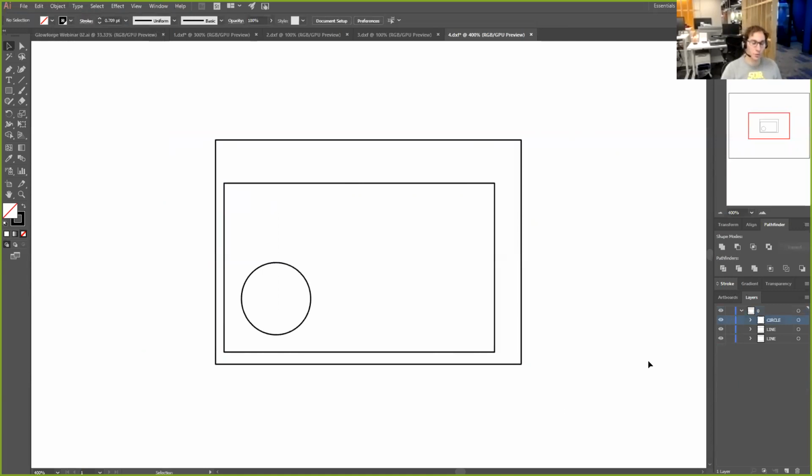In truth, this will work even if you don't join the path altogether. It's fine. It'll work for the score and for the cut. Actually, for the web interface for Glowforge, it'll work no matter what. But honestly, it's a much better practice to join all those paths. And I think you'll have a lot more control over the end result. And so I'd encourage you to just join all the paths. I think that's the way to go.